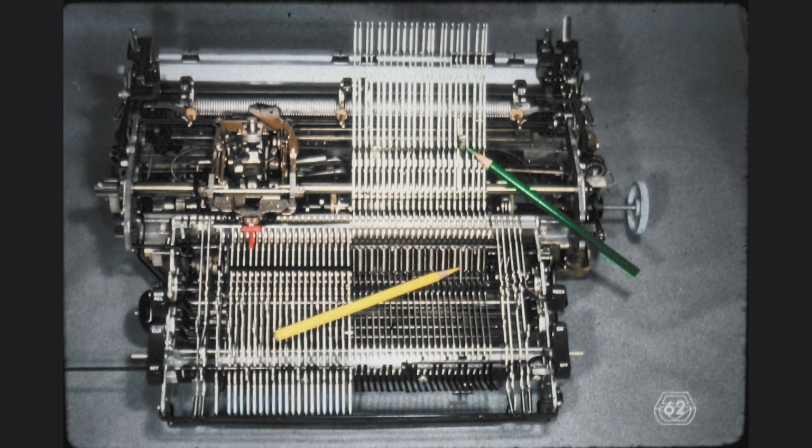Since the cycle clutch latch fails to reset into its rest position, the print operation is repeated for as long as the keylever is kept depressed all the way down. Be sure to notice that the repeat lug is kept well lubricated. And notice also the somewhat stronger and longer spring needed for the restoring of the repeat key interposer.